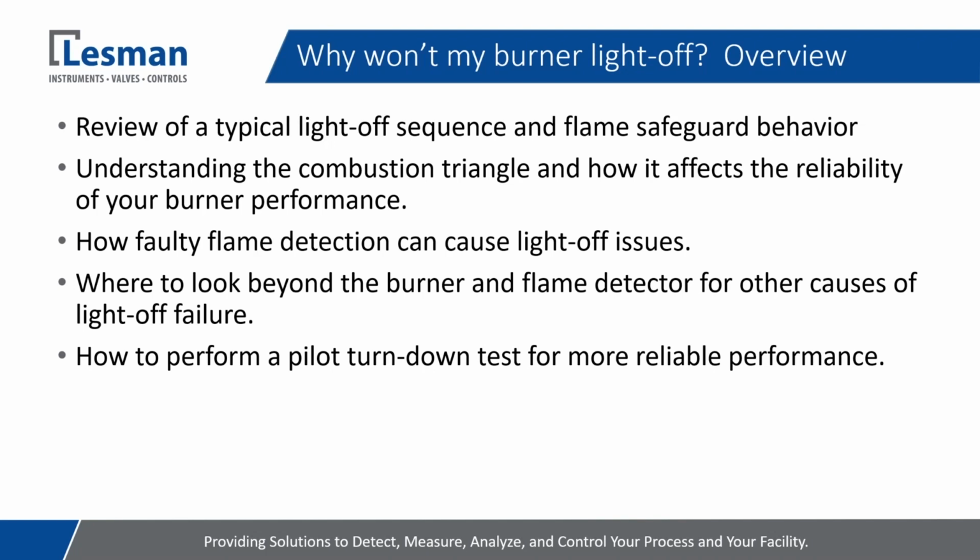I also want to take a step back and look at everything else that's going on in the system outside of the burner, whether it's influence from the combustion chamber or any other electrical influence that could affect the light-off procedure and cause light-off failures. Just give you an idea of some other things to take a look at and consider. And for optimal, reliable, repeatable performance, I'll just do a quick review of the pilot turn-down test for you guys.